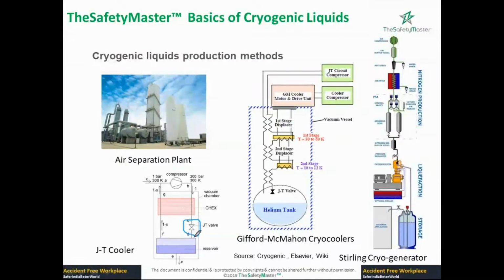Okay, now in Joule Thomson, what happens is this high pressure is suddenly dropped to very low pressure. So you'll form liquid here and vapor on the top. And the vapor moves back, and it's still cold, right? The temperature drops as well. So the vapor will go up and cool the incoming gas. So this is a cyclic process which keeps happening till a sufficient amount of liquid is produced. And that's how the JT cooler works.